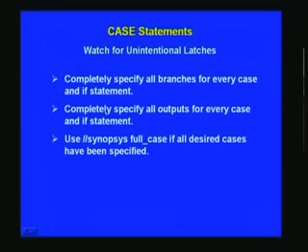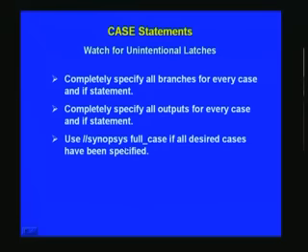Similarly, completely specify all outputs for every case and if statement. We have seen this also in the always block earlier using case, where we had 8 outputs, D0 through D7, and we took care at every case statement that we reset all other unwanted outputs, other than the one which we wanted to set high. That is what it implied here. And use full case if all desired cases have been specified.